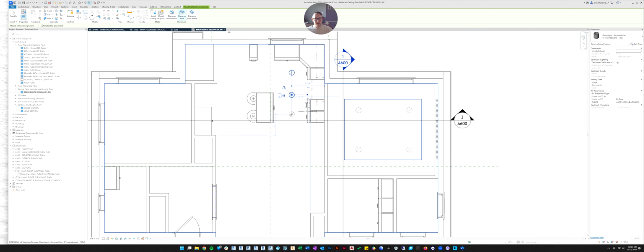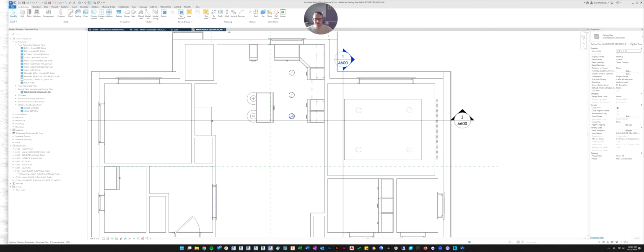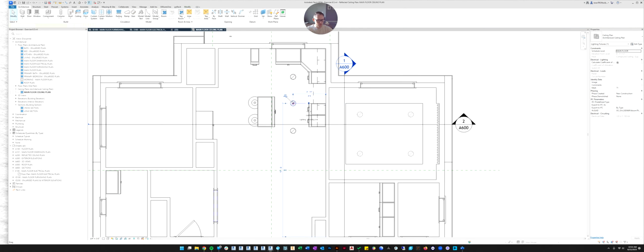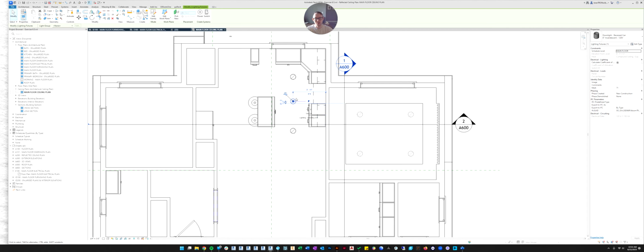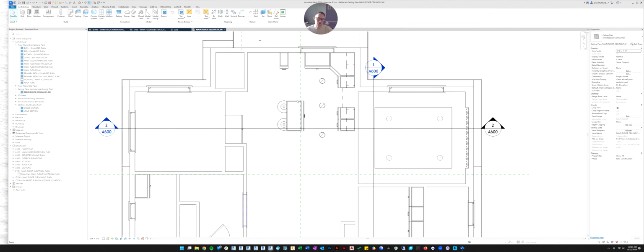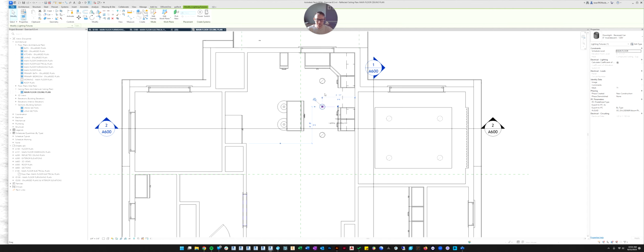Electrical plans, I'm not going to lie, are a little bit frustrating in Revit. And you can see why. Because I need to shut off the underlay so that I know I'm getting the right face. And the reason it's annoying is because of these families. These are not great families. If these families were built right, I'd be able to place them in my floor plan view, and it would automatically go to the ceiling only and not any surface in the view. That's the reason it's frustrating. So if the families were built a little bit better, but they're not.